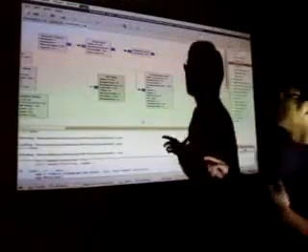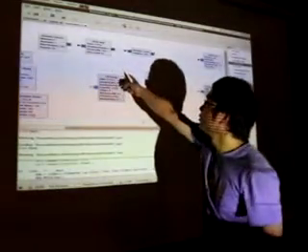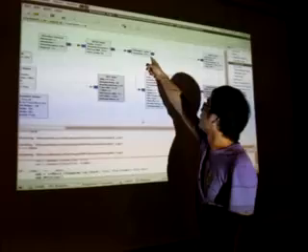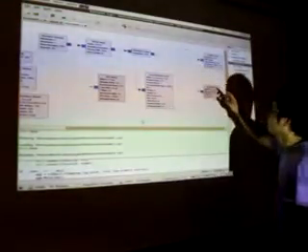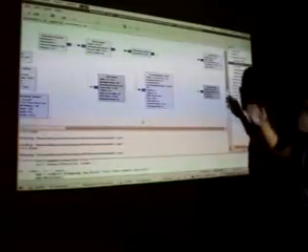Yeah, this one is a little complicated. I generate the random source here, and the random source will be modulated by the DPSK modulation, and then it will multiply by a constant, and then it will be sent to the USRP2 sink and transmitted.